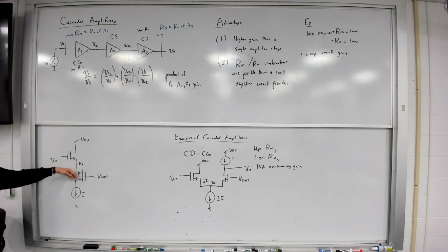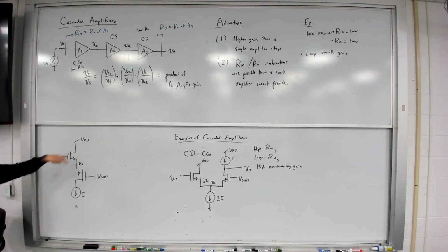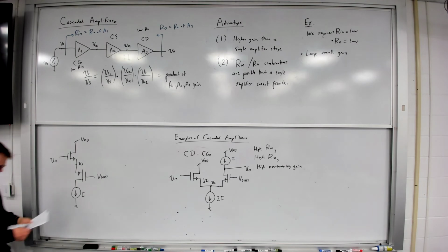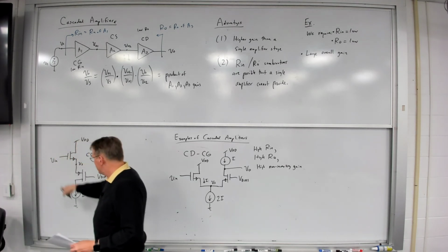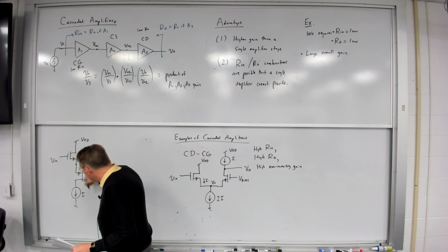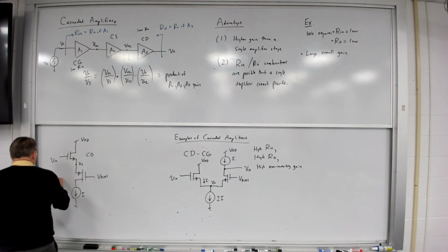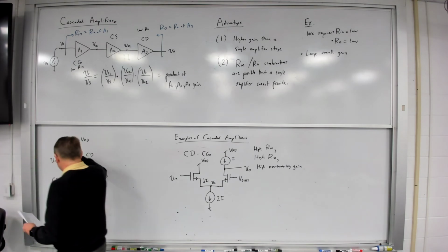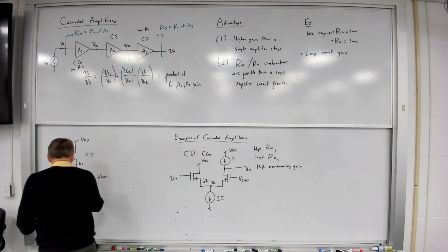What's the load? It's not a resistor, it's not a current source, it's the other transistor. That's the load that's connected to this common drain amplifier. So here's a common drain with an NFET, and then down here I've got a PFET. It's taking inputs going into the source. I've got V bias here. I take the output at the drain.